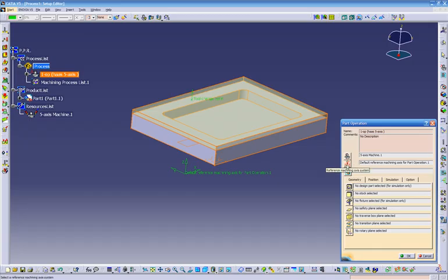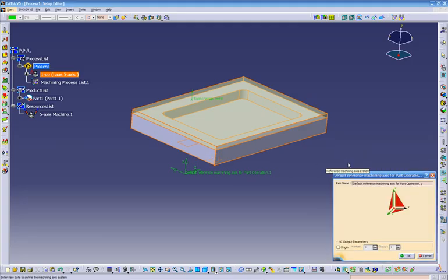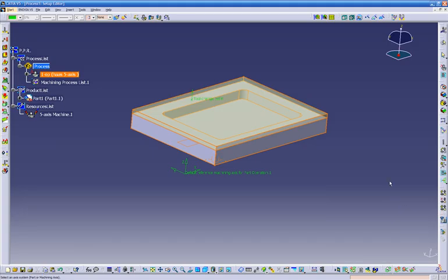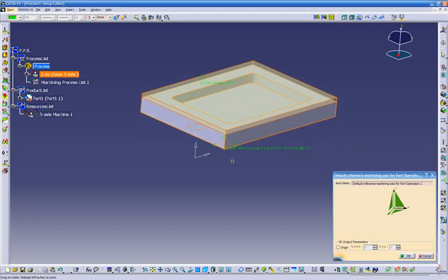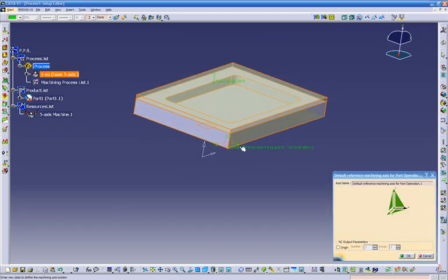Now we have to go next to create our axis. See, our axis right now it's over here, but we have to make sure we specify our new axis. So let's click on the axis and click anywhere on the red area. Okay, and it's going to ask you to select, on the bottom left hand corner, it says select an axis, and we just click on the new axis that we just created earlier, and automatically it's going to snap in place.